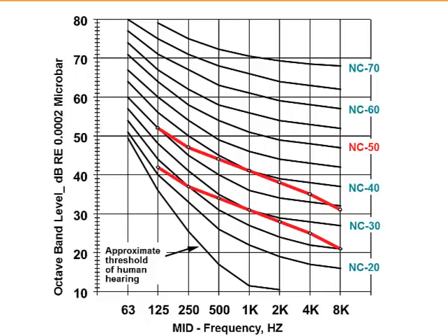device. According to AHRI standard 885, manufacturers are to assume a 10 dB room absorption in each octave band when presenting catalog data for air outlets. This is meant to approximate the room effect of a standard office with a lay-in ceiling, commercial carpet, and some furnishings. If we make this standard 10 dB deduction, we find that our product now produces an NC 30 sound level, and that's how it would appear in most manufacturers' catalogs.